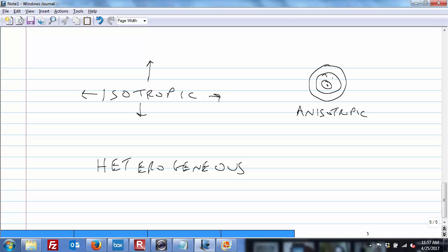If you look at a wood structure, if we just take a cross section, it's always easier to split the wood along this direction, right? Versus coming in with your axe, it's going to be much harder to penetrate that direction. And we also know that water flows preferentially this direction in wood versus radially. It flows axially rather than radially.